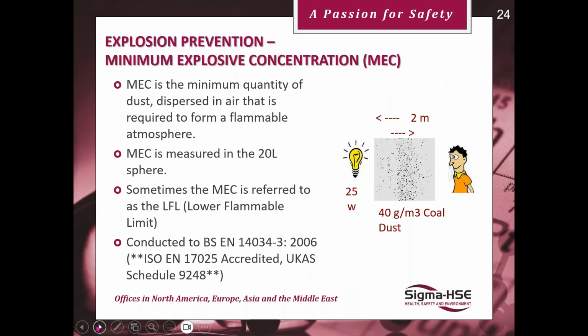Look at the minimum explosible concentration. This is the minimum quantity of dust dispersed in air that is required to form a flammable atmosphere. As I said, similar to the LFL or LEL for gases and vapors. And it's measured in the 20-litre sphere.